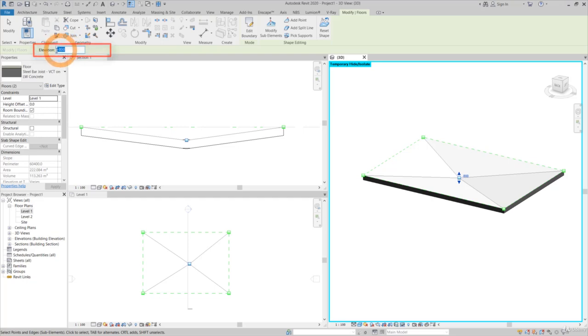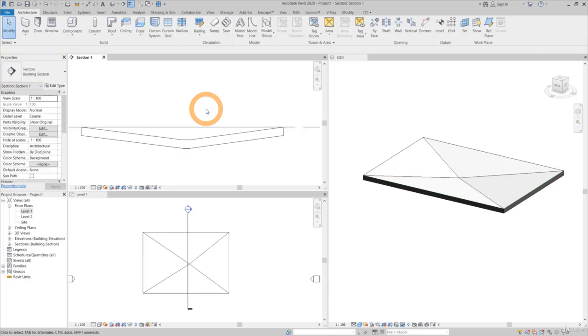As soon as you change the elevation value, Revit resolves the new surface by triangulating it. If we switch to a 3D view, it is far easier to see what is going on. You can envisage that this point may represent a drainage point in our floor that we want to slope down.